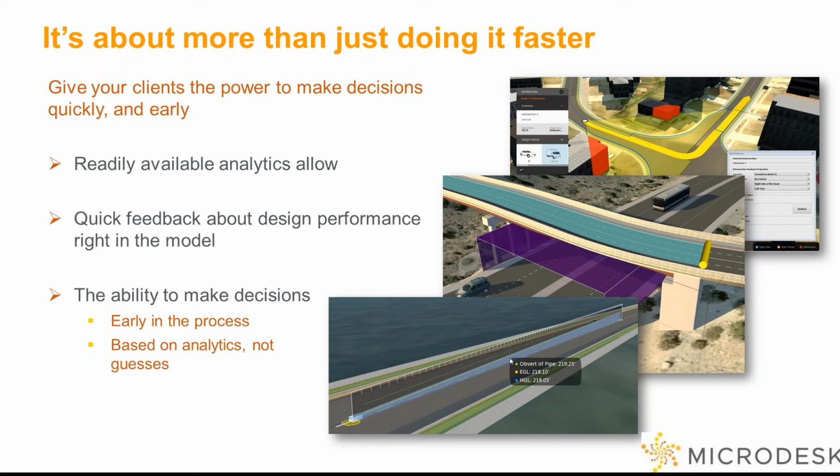The second one is showing bridge clearance, and it's going to allow us to visually demonstrate what the clearance is going to be underneath that bridge. And then the third one we have is actually showing us the performance and the capacity of that culvert underneath the roadway at that given time. Again, fully understanding what it's doing with HGL and EGL content. So that's really nice. Helps us to really understand what we're proposing and make better decisions about what we're doing.